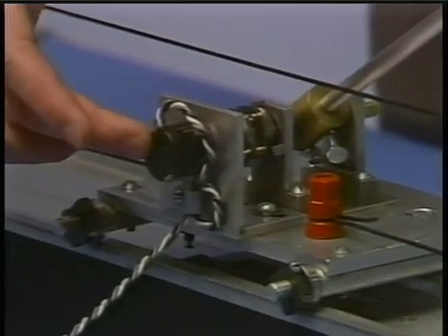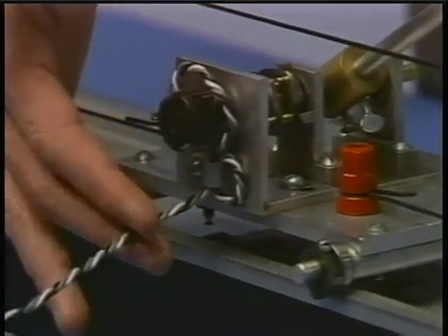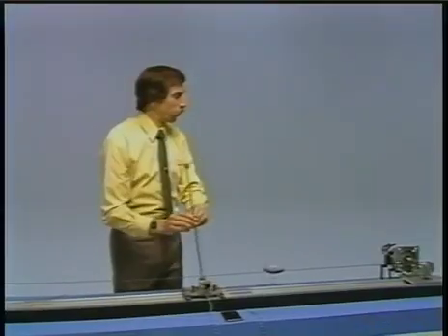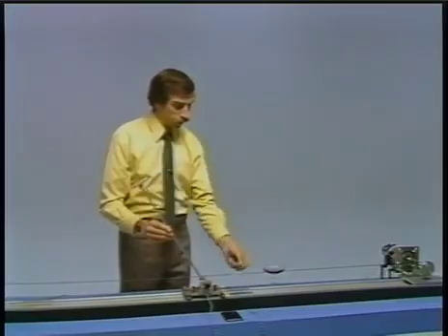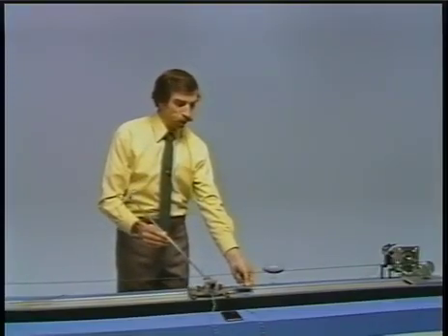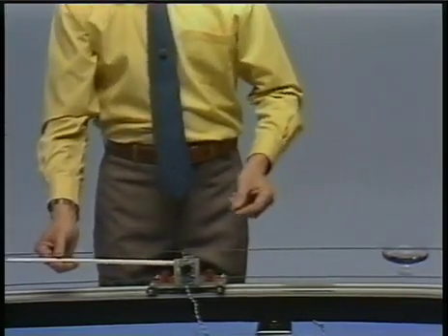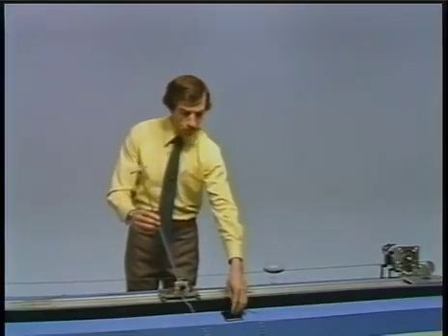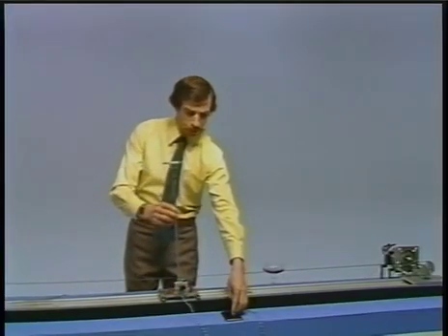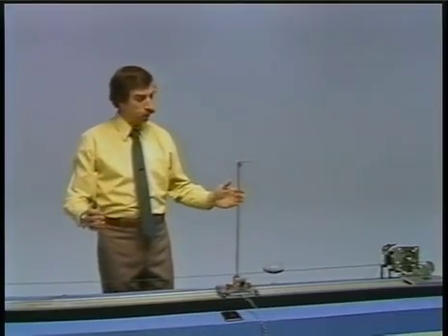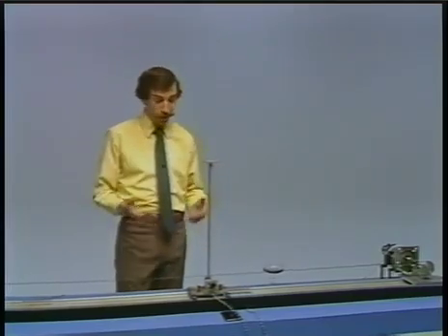And the measurement of the angle is fed back through this wire to a motor that we have at the other end of the table, and then that motor basically is used to provide the acceleration to drive the cart. Okay, well, let's turn it on, and when we turn it on, it'll take just an instant to stabilize. And fortunately, we have the constant set right, and there we have now the stabilization of an unstable system.